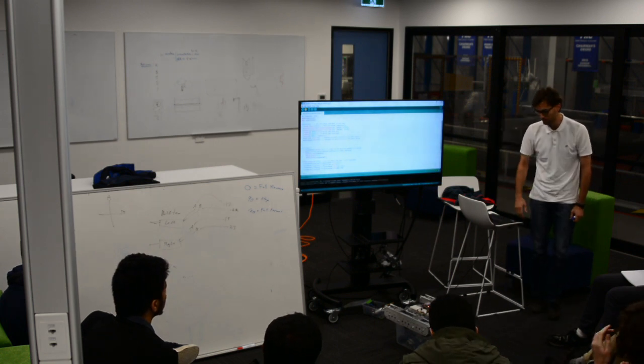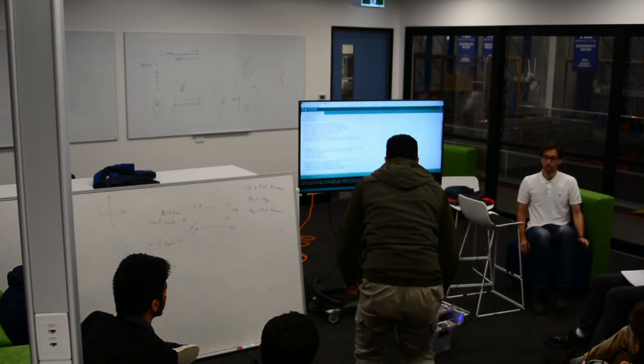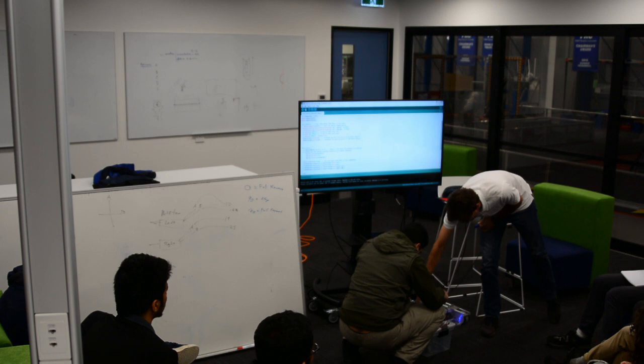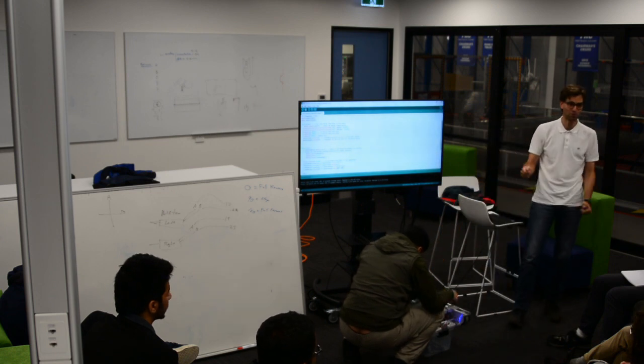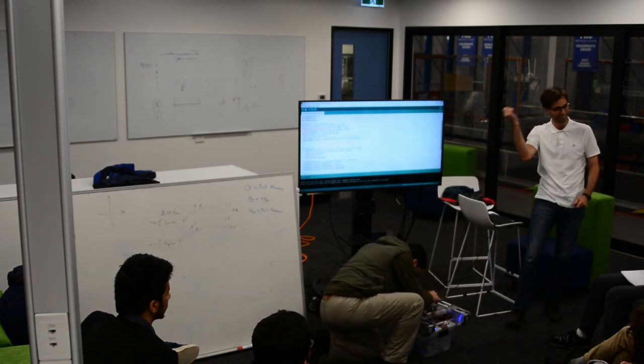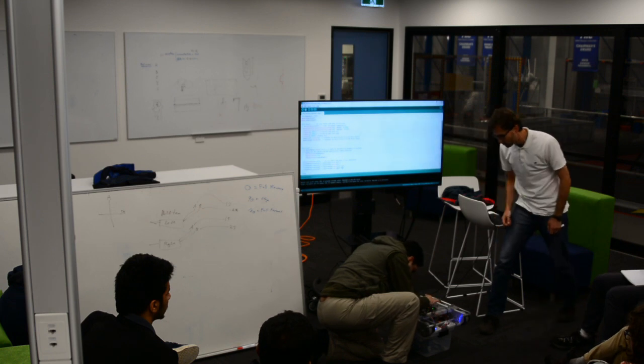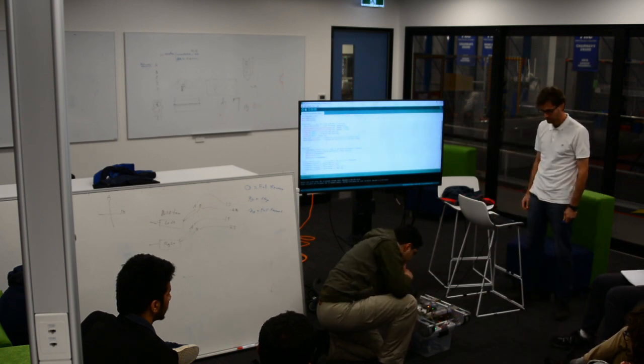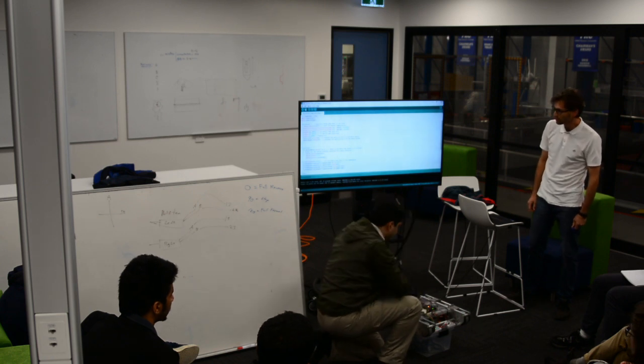Let's dump that. And in fact, why don't I get someone else to do the enabling? Someone else move pin 6 to the red rail. Remember that these breadboards are split down the middle, so I spent 10 minutes using this side of the rail and not figuring out, like, going through wires. Like, this wire must be faulty. So yeah, just move that one to the red side.